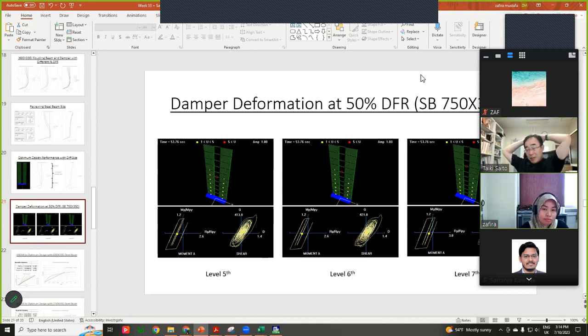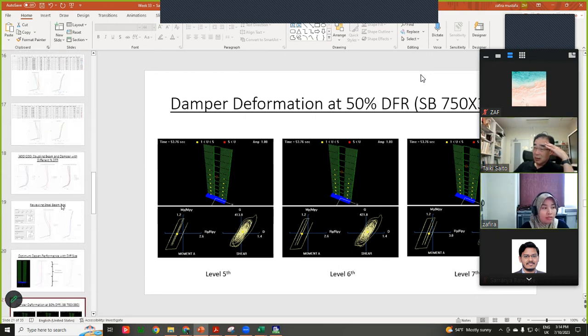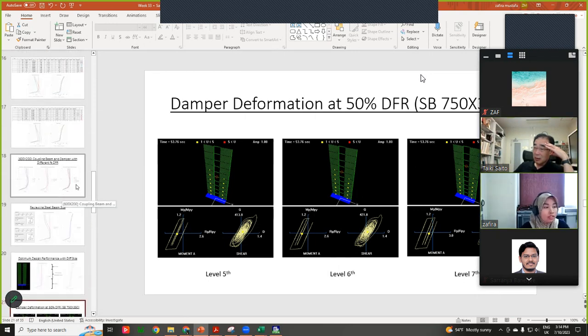If you want to discuss optimization, you need an objective function, like how much energy dissipation. Yes, this is the response, but also the amount you reduce the cost. Right. It's not so easy to find the optimum distribution. So we stick with the previous approach, the damper along the height.